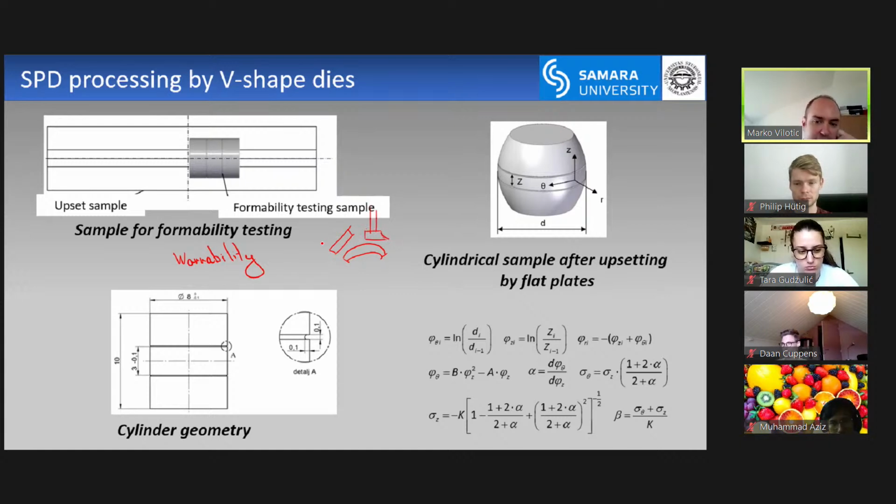If a material is less deformable, with less formability, then you have to use a higher number of operations and smaller strengths. So for us who deal with metal forming, workability is very important. Also, the higher the formability and workability, the cheaper the processing becomes, because you have a smaller number of operations.